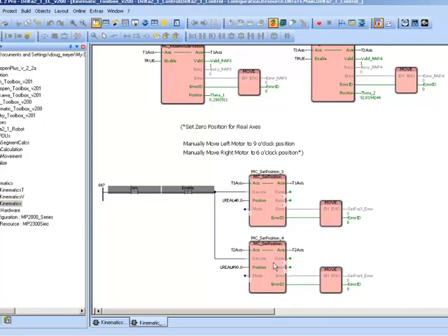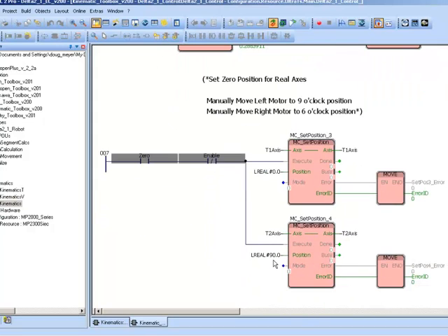And right now the template sets up a 0 position physically. You have to move the mechanism into some sort of physical spot. So on the real application, maybe you would use some sort of a stop, to go to some position and define it. For our demo kit, we decided we're going to move, as you look at the left motor, to the 9 o'clock position, and that's going to be an angle of 0 degrees. And the right motor, you move it straight down to a 6 o'clock position, and that's going to be a position of 90 degrees.